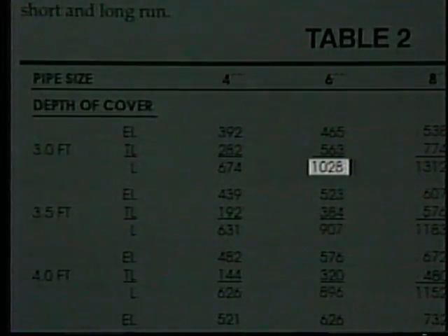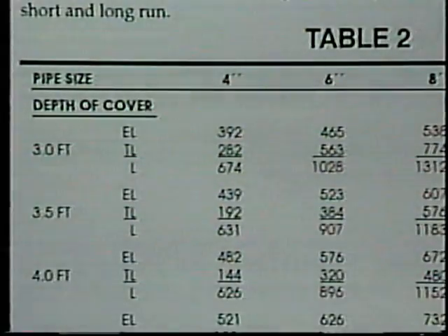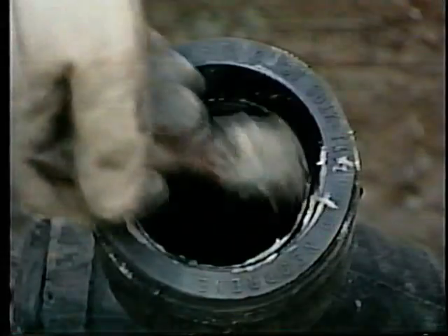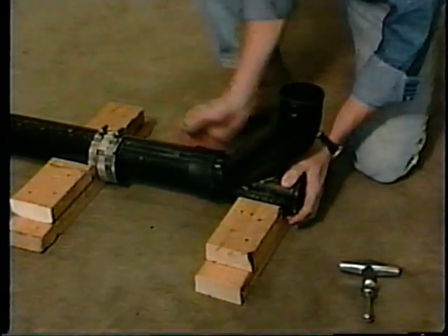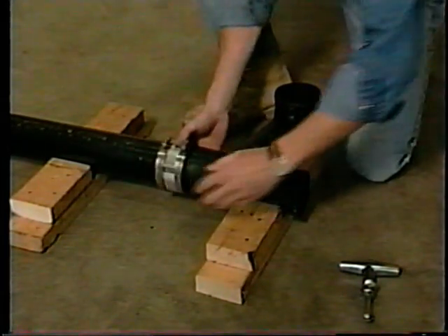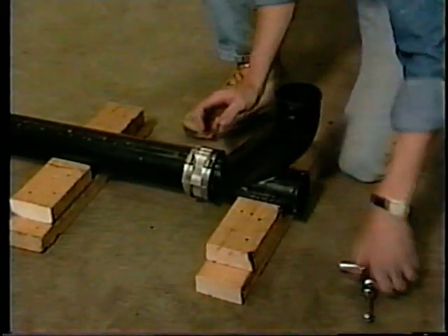Again, adjustments to backfill and compaction are necessary for the plastic pipe to carry the combined weight of the earth load and live loads. Cast iron requires no additional support. Cast iron offers the greatest margin of safety for the owner, architect, engineer, and inspector. And remember, most of today's cast iron systems are joined by compression joints or hubless couplings, which make the installation just as easy as plastic.